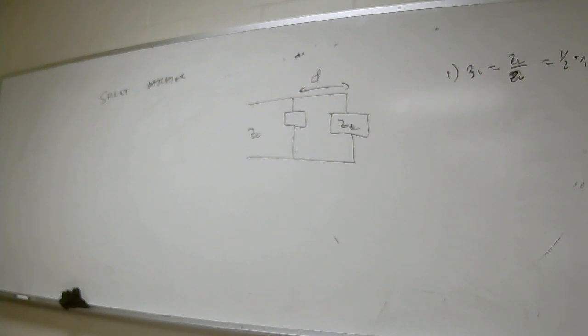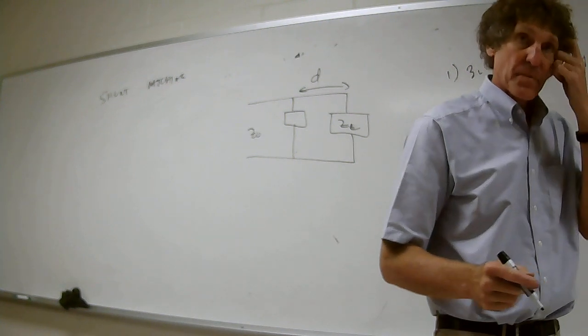This is a constant reflection coefficient. You're going to come to a point that's the conjugate point. It's exactly through the center here where this straight line intercepts your radius circle, and this is YL. It's the normalized load admittance, which is 1 over ZL. You all follow me in this class?